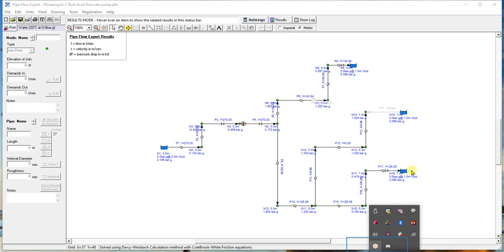So you can add it up, looking at the longer route. You sum them up and get the total pressure drop along that line. If this is the longer one, you use it to size the pump. So with this, we can size our pump.